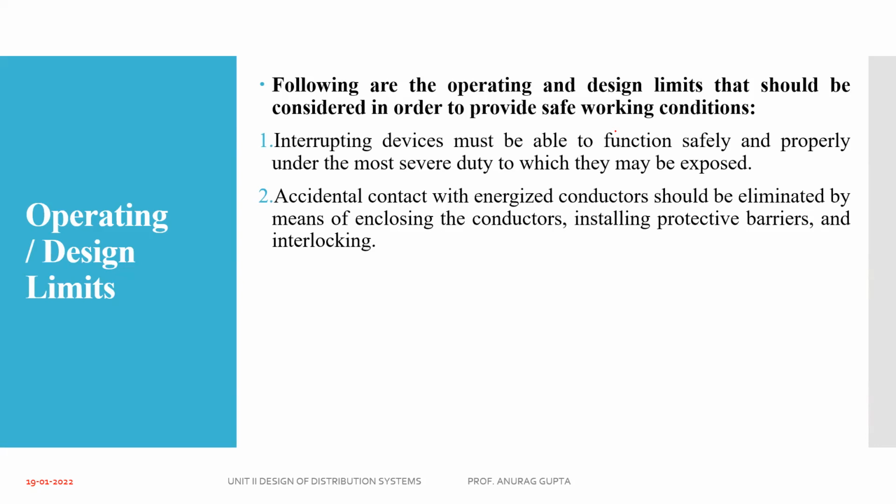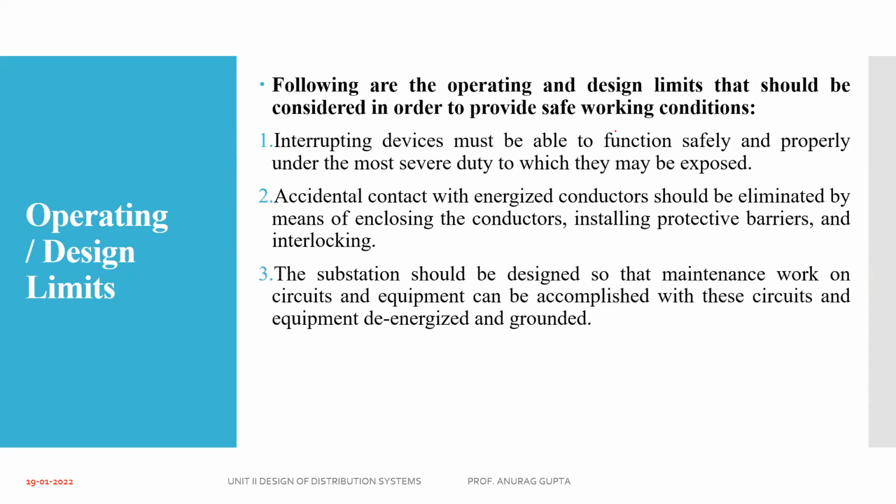Accidental contact with energized conductors should be eliminated by enclosing the conductors, of course, with the help of any circuit breaker, relay system, or bus bar that we can use here. Installing protective barriers and an interlocking system must be there.